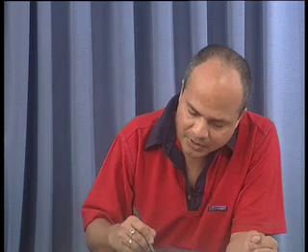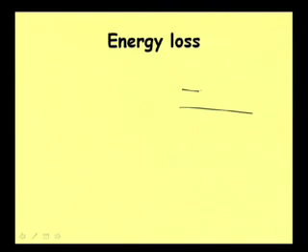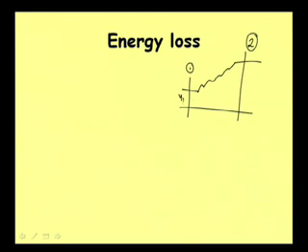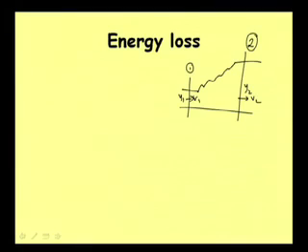Well, so how can we calculate the energy loss? Let us see first. Say this is the hydraulic jump, this is our upstream section 1 and this is downstream section 2. We give the depths as y1 and y2, and the velocities as v1 and v2. If we consider this as a rectangular section, then our expression becomes simple. Otherwise, of course, we can always find it for a different section also.